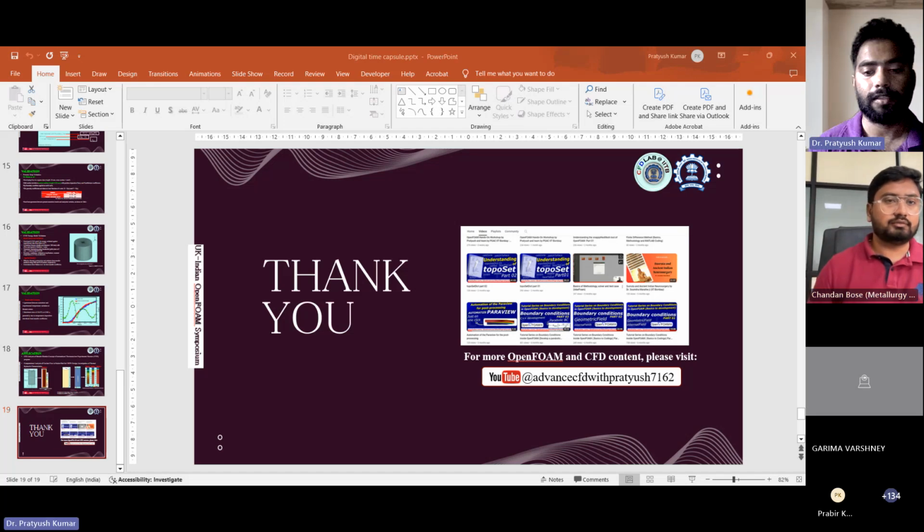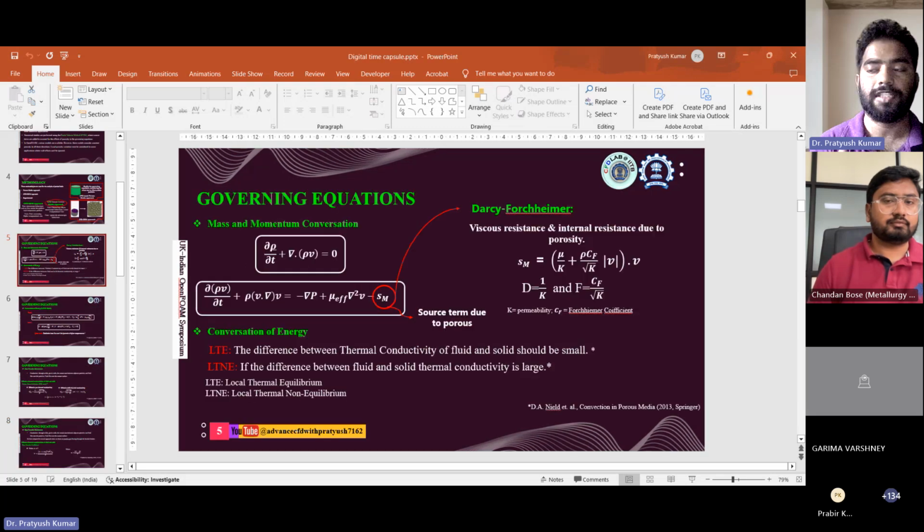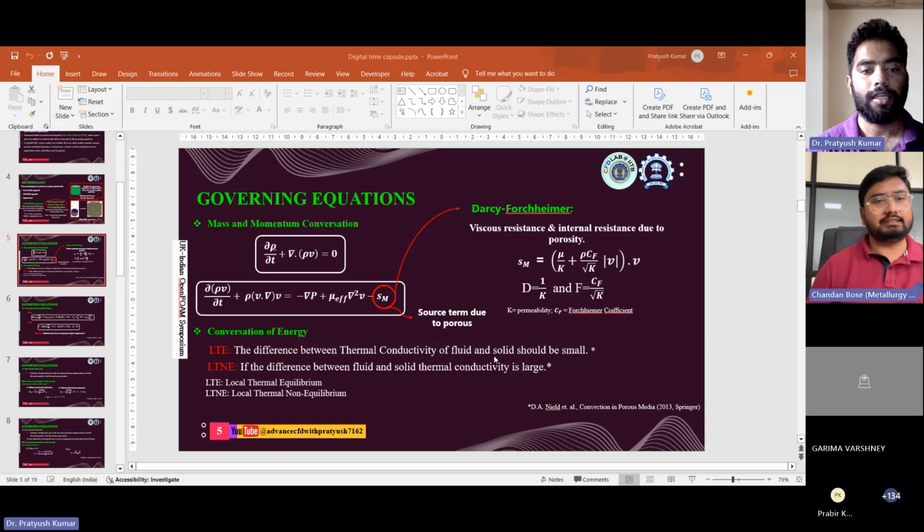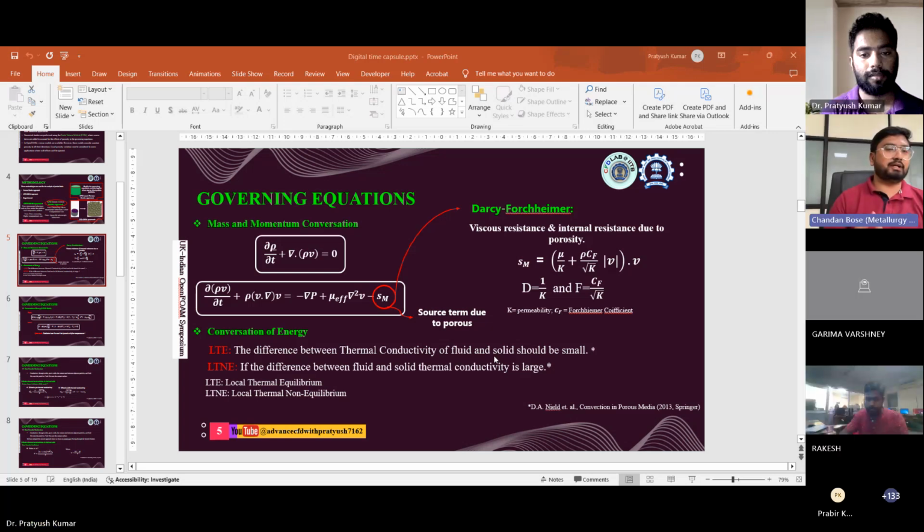Sir, actually, I said that my focus is only on the packed bed. In a packed bed, the Darcy and Forchheimer coefficients are a function of the porosity only. In the Bejan paper, a correlation is given using the particle diameter. My point is, of course, porosity and permeability are correlated. They have some empirical relationship, but we cannot directly predict the porosity from permeability. That was my comment.